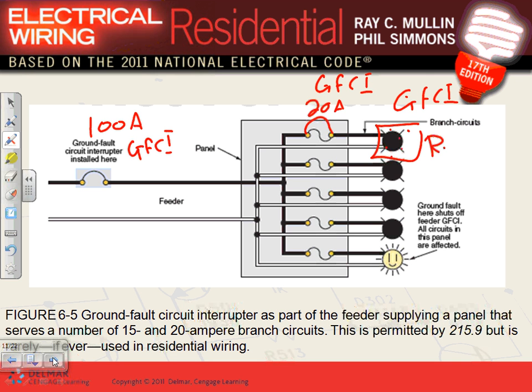99% of the time, or 90% of the time, you have a ground fault circuit interrupter receptacle in the US. Sometimes we have a ground fault circuit interrupter circuit breaker, and sometimes you have a main. The main is a circuit breaker. The main is not commonly used here. In other parts of the world, they put a GFCI on the main. Did they tell you about what I used to do when they put them on the main in Jerusalem?